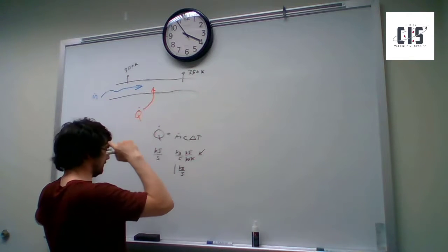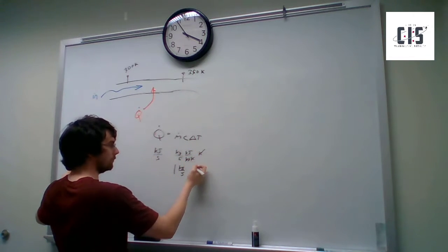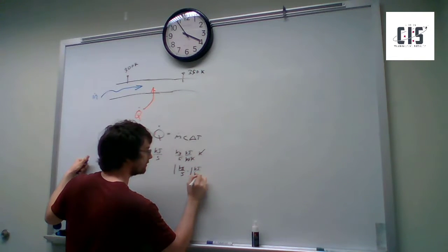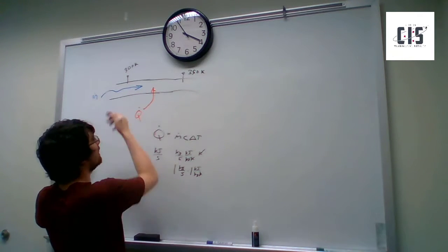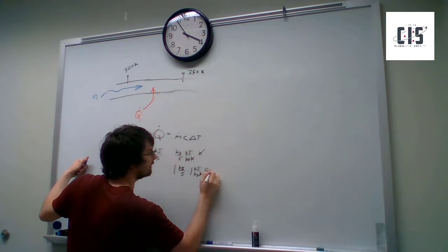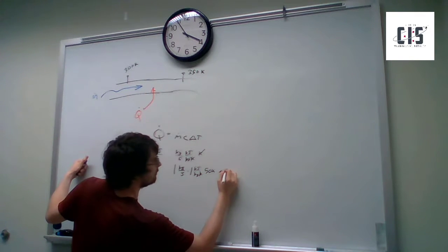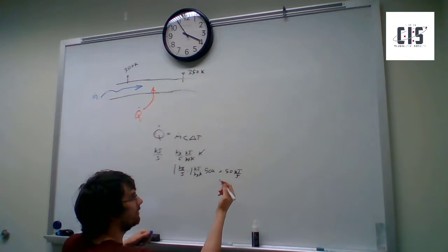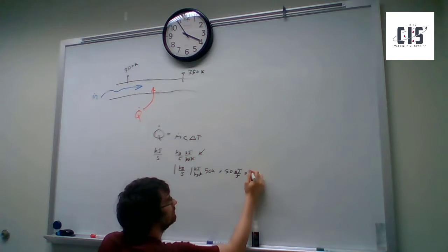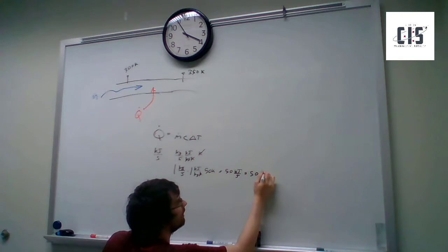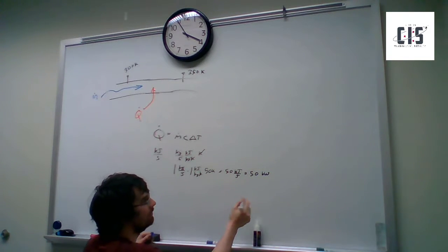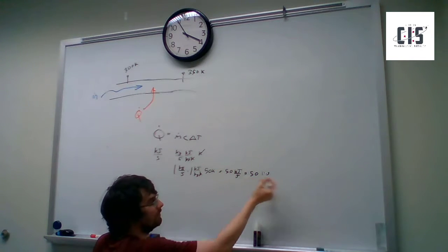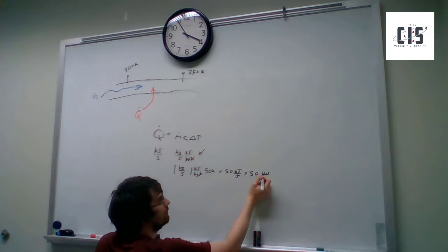Nice. So if it's 1 kilogram per second, and you're transferring, I'll use the same, times 1 kilojoule per kilogram Kelvin, and then multiply it by 50K, the temperature is increasing by 50K. We get 50 kilojoules per second, which has its own special unit of 50 kilowatts. So a watt is a joule per second. It's 1,000 joules per kilojoule, and similarly 1,000 watts per kilowatt.